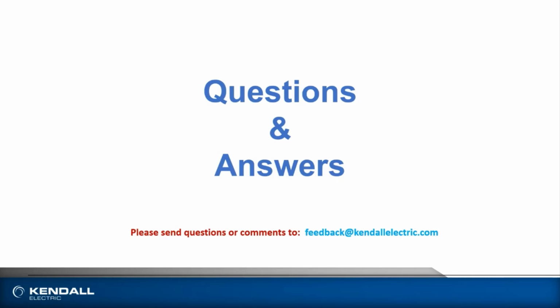And then the quick key modes. I do not know. I've gotten so used to just the point and click with the mouse. I didn't look for quick key modes. I don't know, Rob or Ryan, do you have any input on that? Rob, you would remember from doing quick key stuff with the AI. I think you can do XIC and TON, I believe, if that's what I think Mike is referring to. But as far as quick key specifically, I don't know. Like an Alt or Control plus certain keys, I know that functionality is still in RSLogix 500. I haven't used it in a long time, but I haven't seen if I can do that in CCW, just because I tend not to use the keyboard as much.